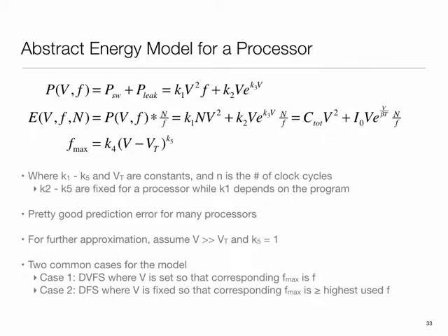Okay, and let's make all simplifying assumptions that it's a RISC processor, one instruction per clock cycle, and every instruction essentially makes the same power consumption. So they're all fairly reasonable assumptions. For most processors, you don't see much variation instruction to instruction. There are processors where the type of instruction matters, but a very good first order model is that all instructions are the same. Okay.